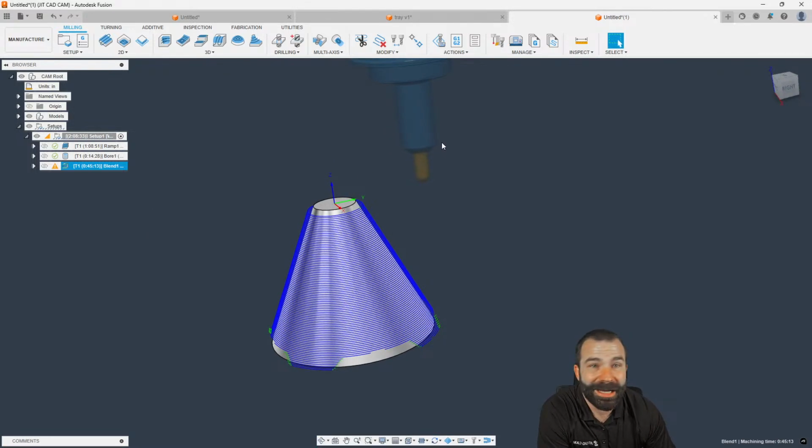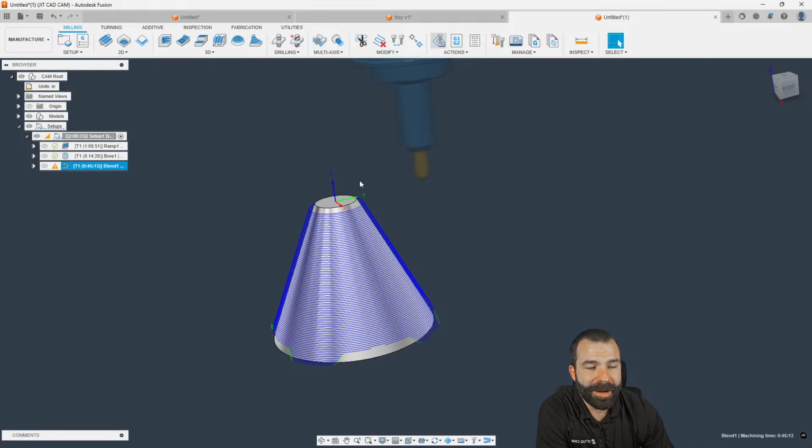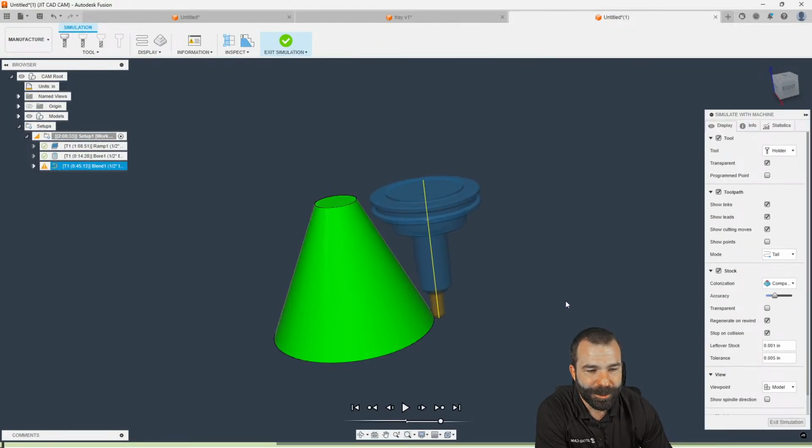Bottom up is a better finish. I've heard that a lot, and I've seen that a lot, especially with mold making. Sometimes bottom up is the better approach. But as Travis has pointed out there, you could use a blend strategy, and that blend strategy does allow you to reverse your order of step over, which means it will actually force a bottom up.